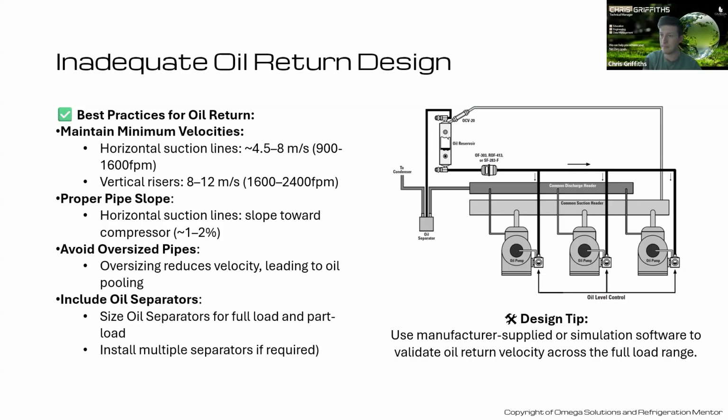Well, what can we do about that? We could install multiple separators in parallel. We could have one separator per compressor, feeding into one or multiple oil reservoirs as well. So looking at these conditions at full load and part load is very important, because part load condition is where oil management is more important, in my opinion. Yeah, and I think in piping design, I know in module 10 of the 12-week course, when we dive into oil management, sizing those oil lines is so vital as well.